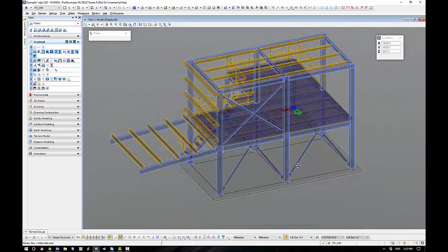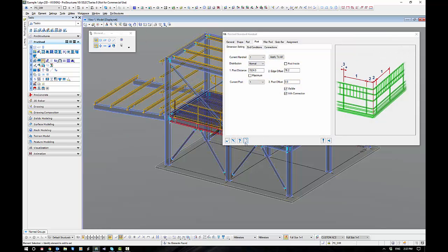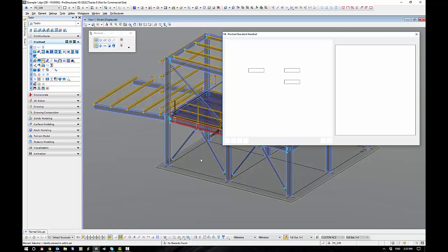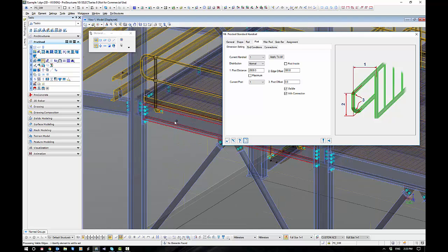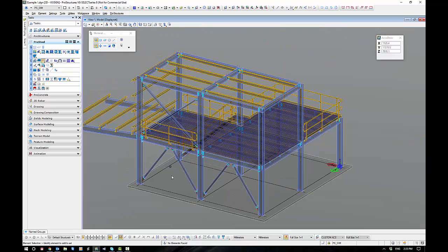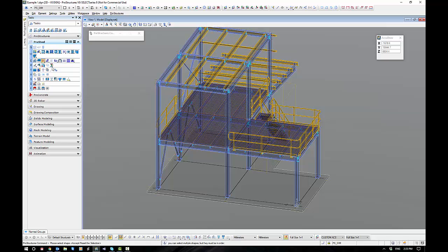After you get the hang of this a little bit, you can start creating your own templates with your own settings, and from then on it's a simple case of select a beam, particularly easy if there's these single ones, come down to your templates. I've got some horizontal runs here with a side offset 130, drops them in with my preset settings, and you just run around and pick the beams that you want to put the connections on. Final thing is, don't forget to edit these. Just select the beam, go to the logical link and edit the connection through the logical link.